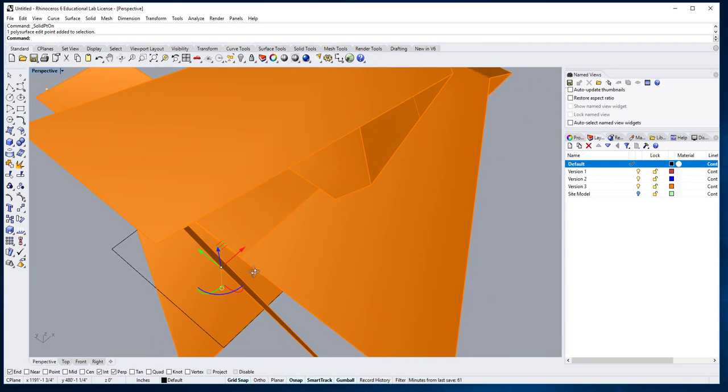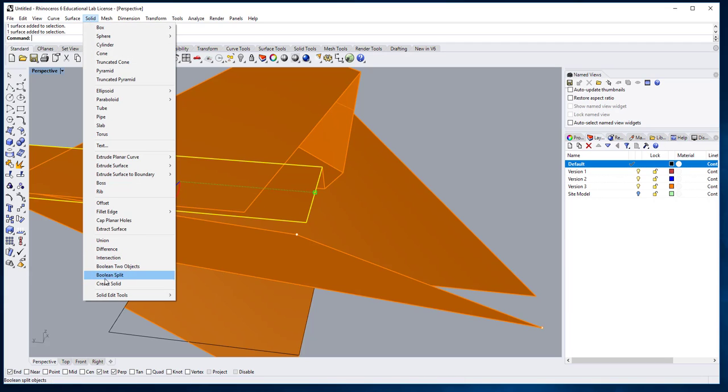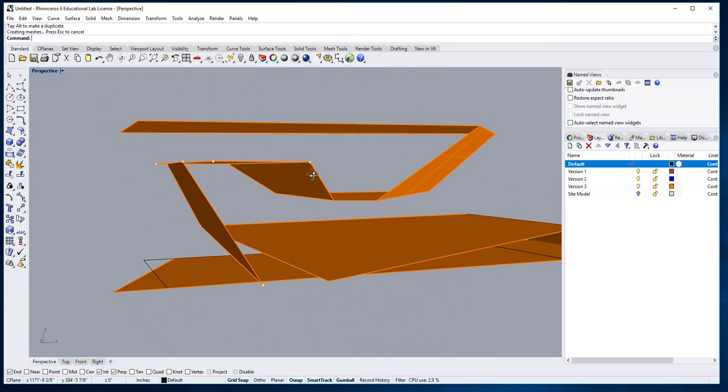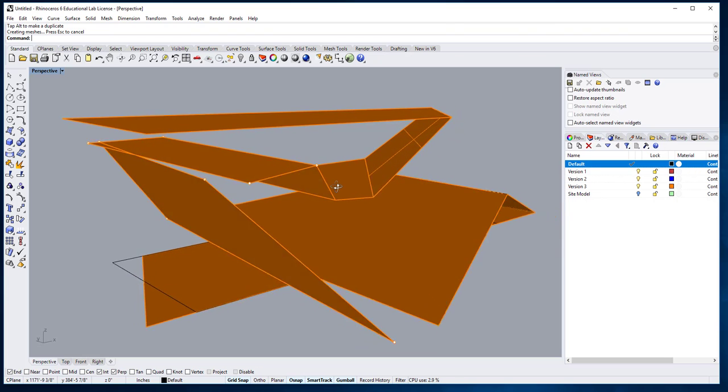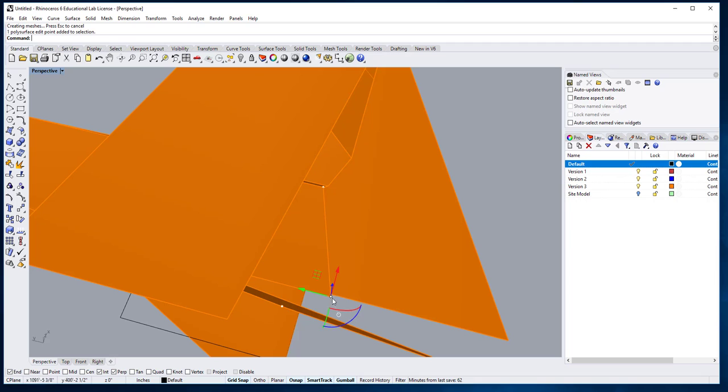Okay, so I can't pull that point forward to get rid of this 90 degree, right? But I can do it here because the gumball is still orthogonal or perpendicular to that shape. So solid, turn on points. And I'm going to pull this guy slightly forward that way. Maybe a little more.